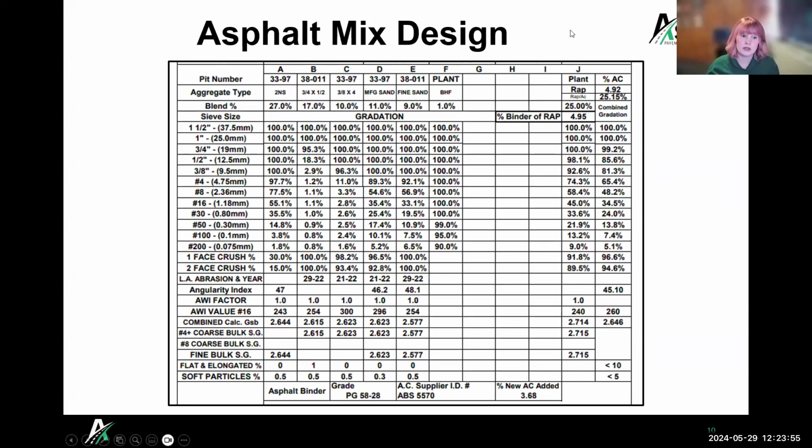Okay. So yeah, those numbers, you should expect that they're not going to be the same on each form. If they're the same on each form, something has gone wrong, or somebody didn't regress their air voids down to 3%.